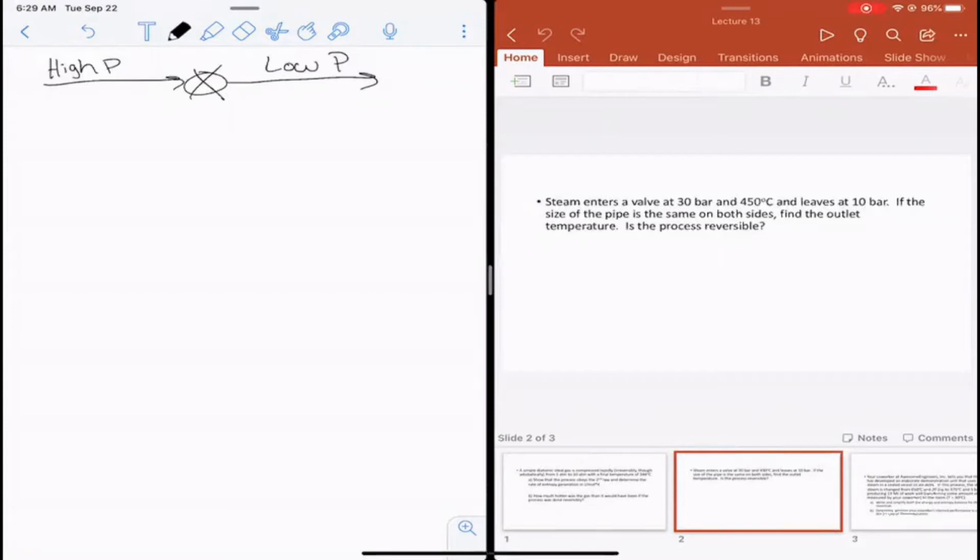If you apply the energy balance, we still start with dU/dt equal to Q plus W plus the sum of the enthalpy entering the system through mass flow minus the sum of the enthalpy leaving because of mass flow, plus the kinetic energy and potential energy.